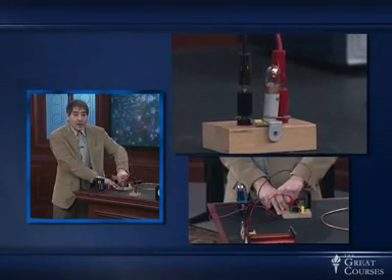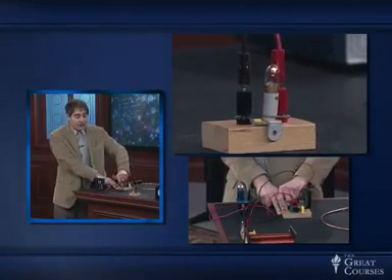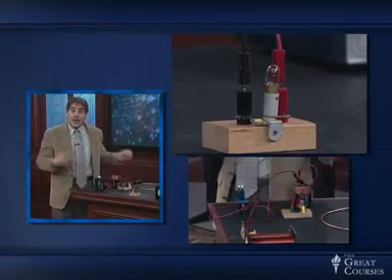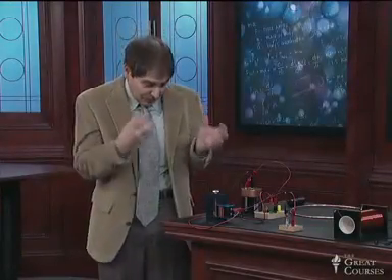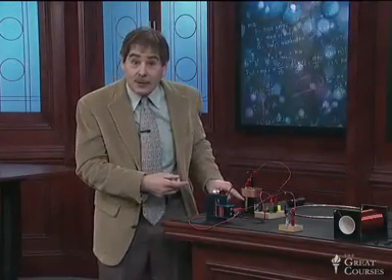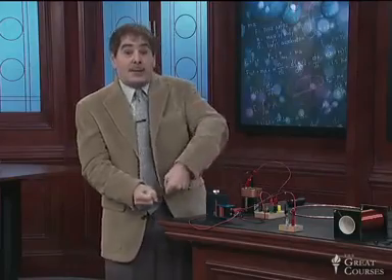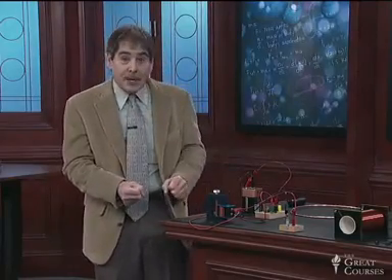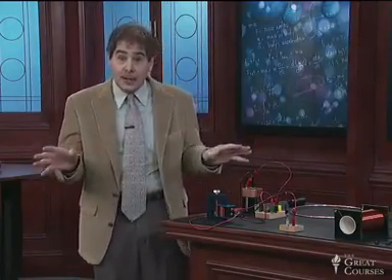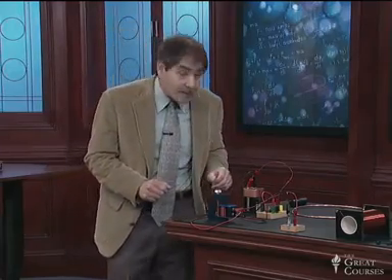Let me do it once more. The switch is closed. I let the current build up for a little while. Bang, I open the switch, and there is that bright flash. And with bigger inductance, even with still 6 volts, and with more current flowing, that could have been really dangerous. We would have seen a big arc across that switch. It can do damage. It can literally electrocute people.